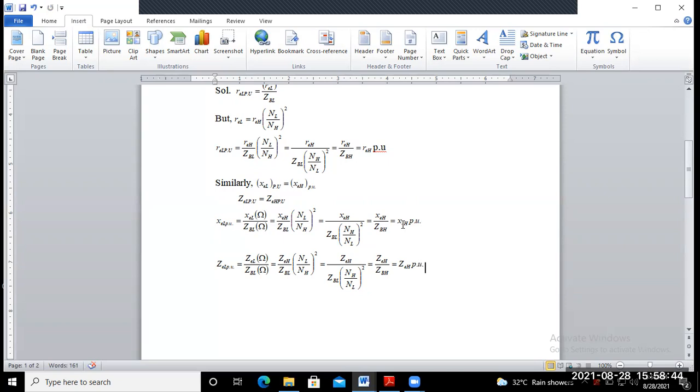All are specified with their power rating and voltage rating. Their data, that means parameters and reactance values, may be given in per unit, but on their own base voltage and base MVA rating. So that per unit value may be converted to another base voltage and base MVA rating.